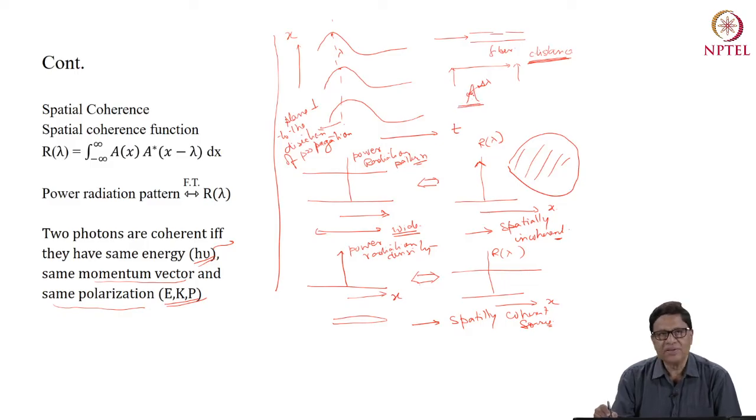But the advantage of a narrow spectral width delta lambda is that in the fiber, the wavelengths inside this delta lambda may not have a significant amount of dispersion when they travel. If it is wide, each wavelength will travel at a different velocity and arrive at different times, so you will see spreading of pulses.